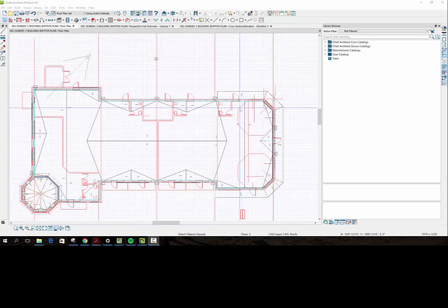High point of the truss. So we'll have the truss manufacturer create a truss with a high point here, low point here, and this truss will maybe only need to be 2 inches lower in order to create that little bit of a slope to get to the scupper box there. And that should do the job.